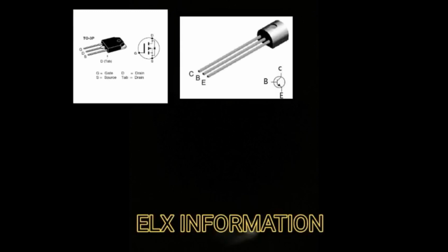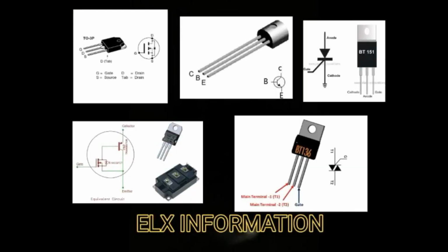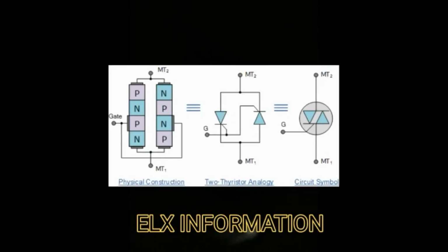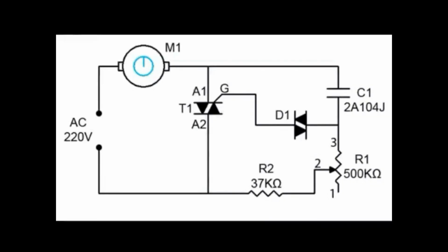Each device has its own uniqueness and properties, and thus they have their own specific applications. In this tutorial, we will learn about the Triac, which is a bidirectional device, meaning it can conduct in both directions, and it is a combination of two SCRs with opposite direction of anode that is exclusively used where a sinusoidal AC supply is involved.